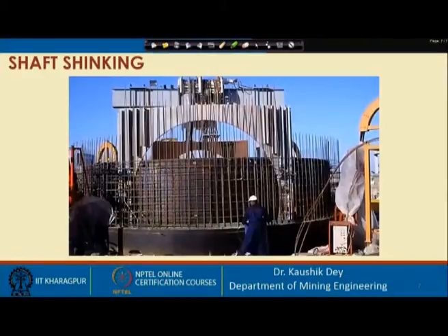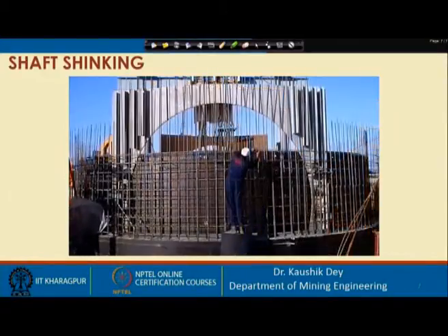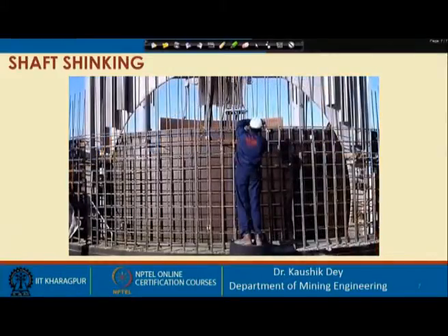This can be an advantage if the shaft is to be used for launching tunneling machines. The shaft wall can then be prepared with a built-in launch eye to exactly suit the tunneling equipment. So this is the in situ concreting, actual photograph.